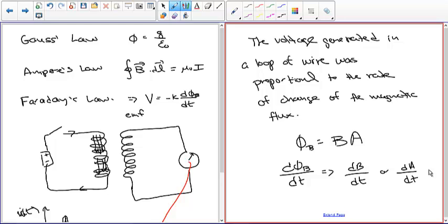Well, hey, that's kind of like a motor, except when we had a motor, we stuck this inside the magnetic field, sent a current through, and that causes it to rotate. In the case of a generator, we're the ones putting in the input, we're rotating it, and what we're getting out is the current, and that's what we do to make all of our great power. We just have to find different ways to rotate it. You can run it by an internal combustion engine, by water turbines, or by wind turbines.